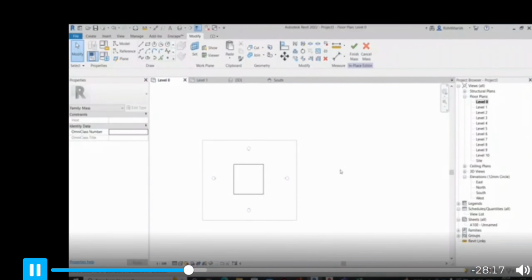Can we set the levels like a reference plane and rotate in that? No, not required. We don't have to complicate it this much. What I want is at every level this shape should rotate by 2 degrees. Now, rather than creating a copy at every level and rotating it, I can just create a copy at level 4.